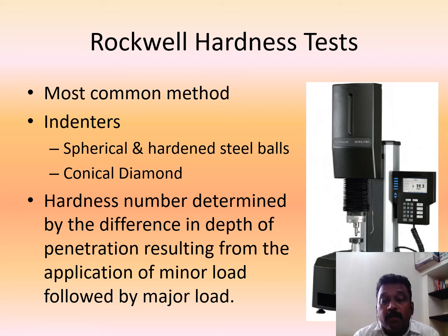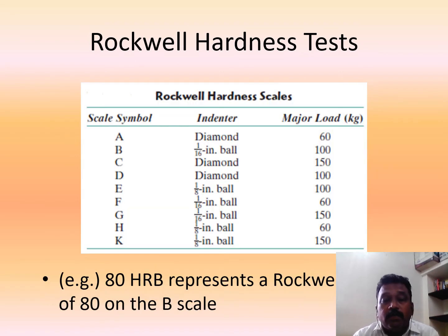of that material. So this hardness, denoted in the form of a number, is determined by the difference in depth of penetration resulting from the application of a minor load, followed by a major load, on the specimen. You can see the Rockwell hardness scales